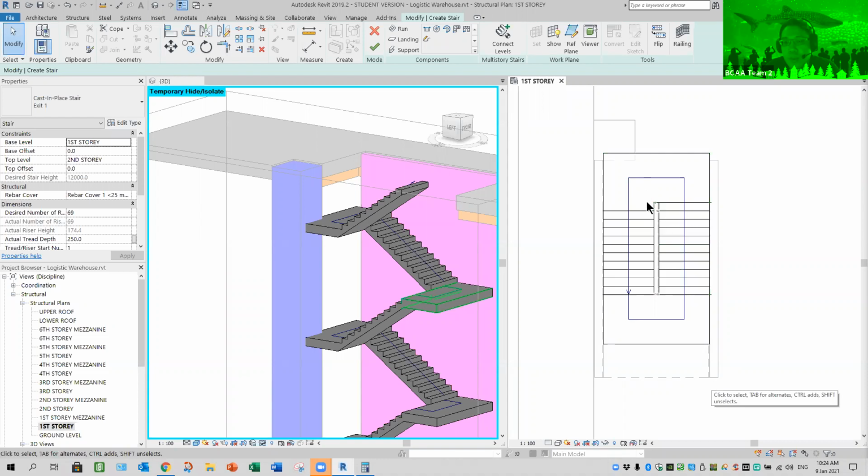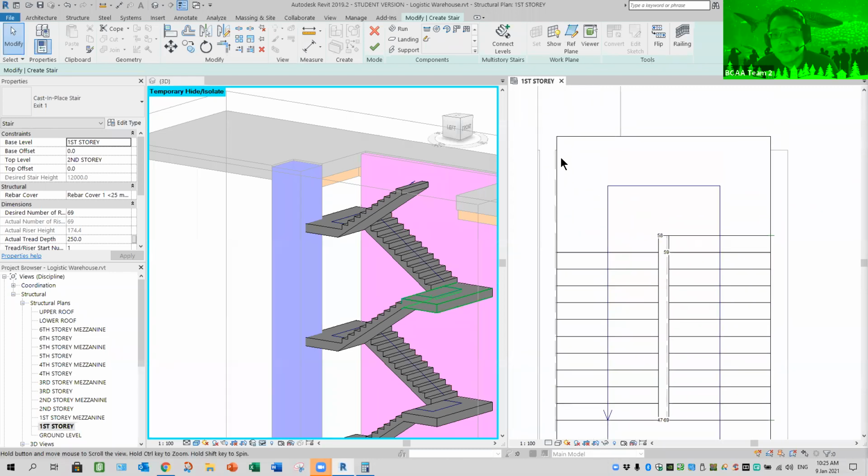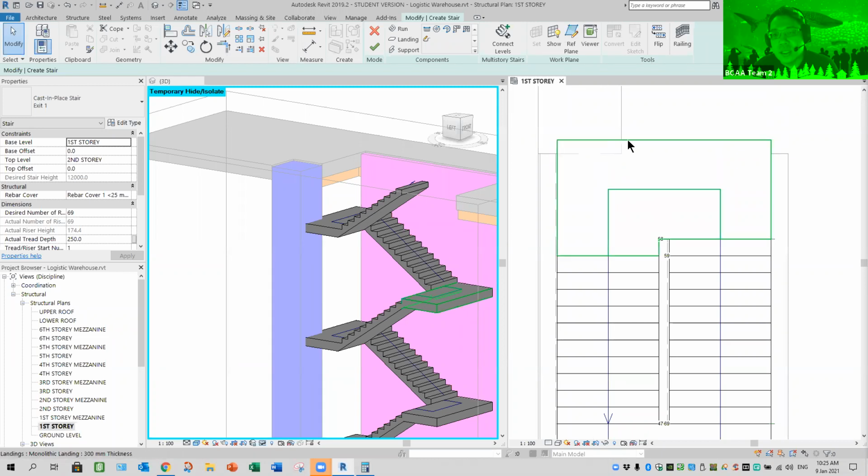All right, so again, you may want to relocate your adjustment, because in your model, this wall here, what we call the curtain wall, means it's glass. So your staircase should not be protruding out. A few ways people do it is that they adjust this to cut short.